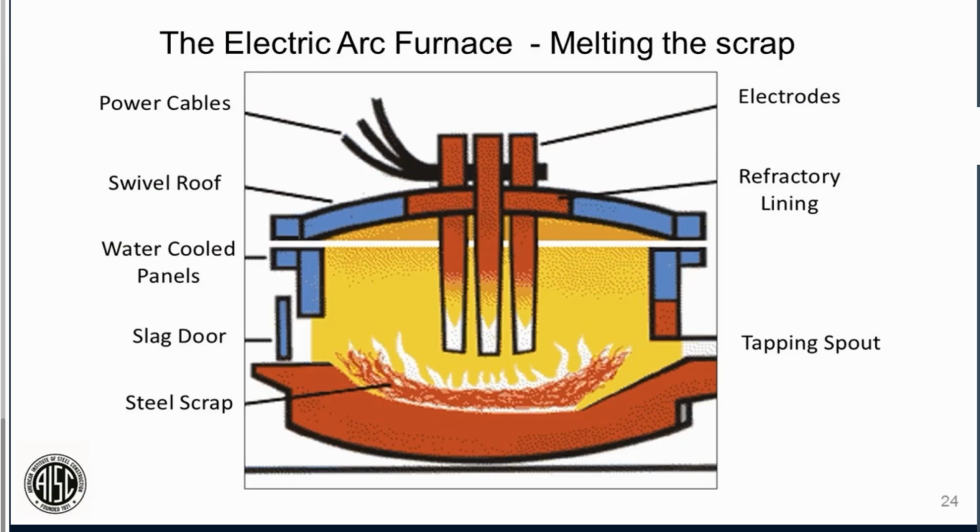So what is the electric arc furnace, and what are we talking about here? This is a little diagram schematic of what an electric arc furnace is, and it has multiple components. What I like looking at is a big three-phase welder. And these big graphite electrodes conduct the arc plasma between all the 3 phases and create an incredible amount of energy and heat. Well, to contain this, we have a refractory roof that swings off so we can put the scrap in with the electrodes.